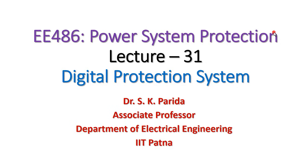In the last lecture, that is lecture 30, we discussed the importance of the sample and hold circuit, and we also talked about the concept of anti-aliasing and the importance of the anti-aliasing filter, because practical signals in the power system, whatever current and voltage signals we collect from the field, consist of many other high frequency signals. So it is very important to remove those high frequency signals in order to avoid the aliasing effect.